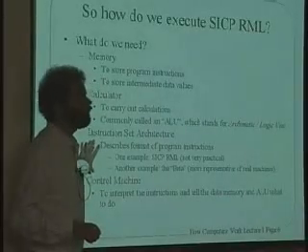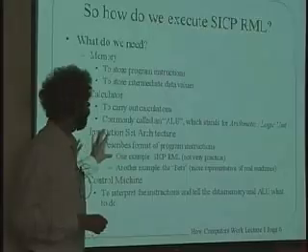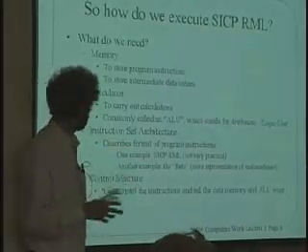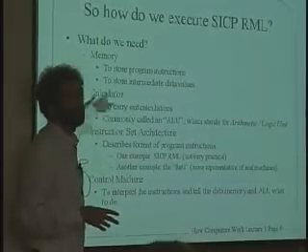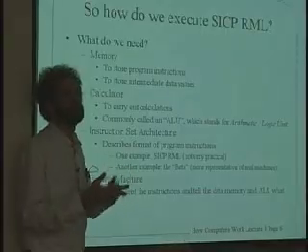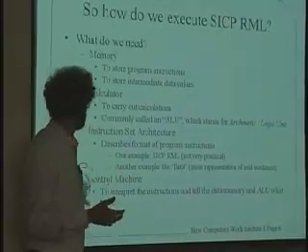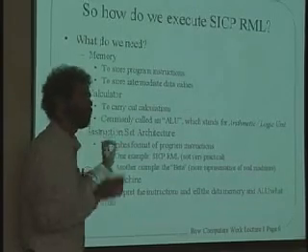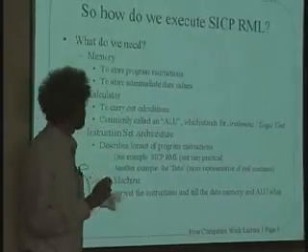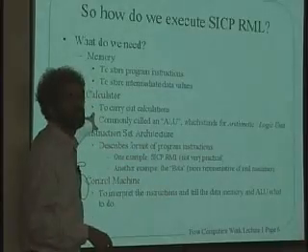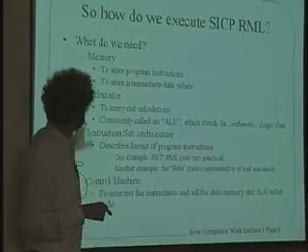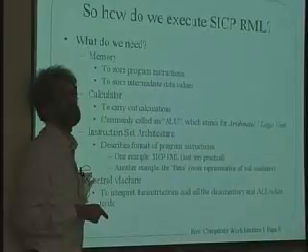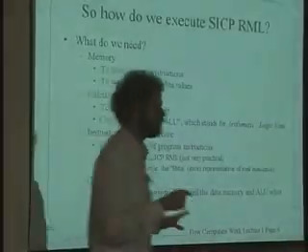Now, once we decide on the meaning of the bits in the instructions, we now need a circuit which is going to look at those bits and control the calculator and the memory to actually execute what we want the instructions to do. When an instruction says add, the control logic will look at the bits of the instruction that we've decided stand for the code for add, and we'll press the add button on the hardware here and press the buttons on the memory to store the results where we want it to go. And what's incredible is that these four things are enough to build a system that we want. That's all that it takes. And that's, in fact, all that we're going to do for the next 3 weeks, is talk about basically those four things.